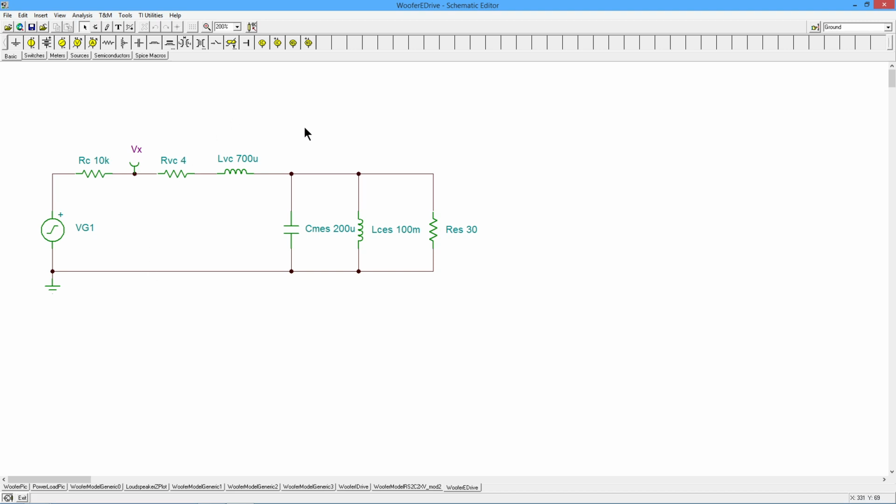You'll just see the sine wave, and you can measure what that voltage is, but you'll know what the current is. So if you had 10 volts peak and you got a 10K, you divide that out and that's a 1 milliamp current, right? So whatever you see for a voltage on the scope, you just remember, okay, that's with 1 milliamp of current. So I can just use Ohm's law and determine what that is.